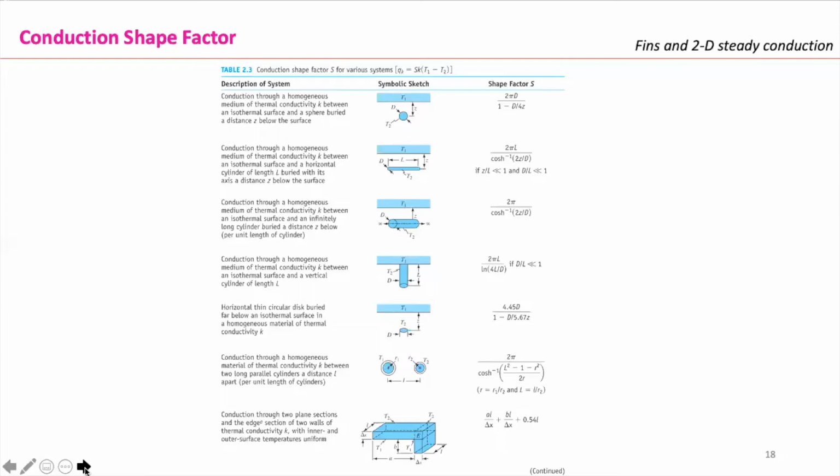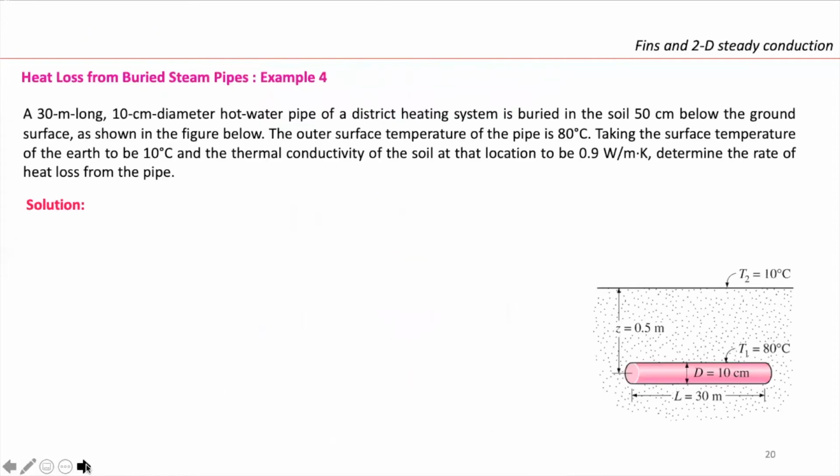Okay? So it's like a Lego problem at the end. So I can do any shape with these shapes that you have in here. We can put together shapes. You add all the shape factors and put it in the modified Fourier. That's the most complicated thing you can face in this type of problems. Okay, that's a simple problem. So you can see how to use the table.